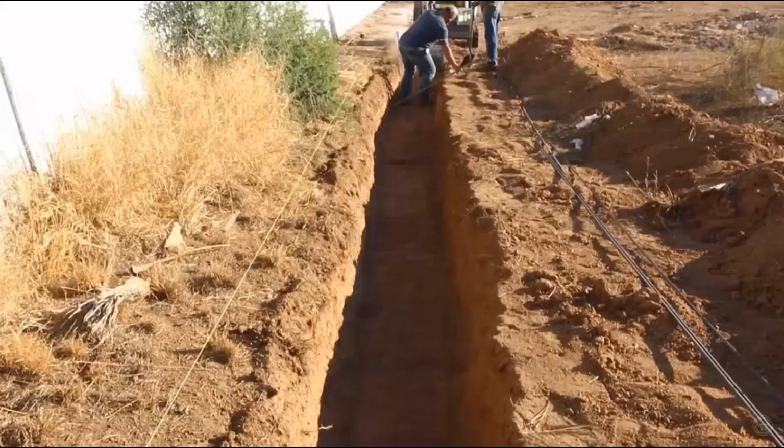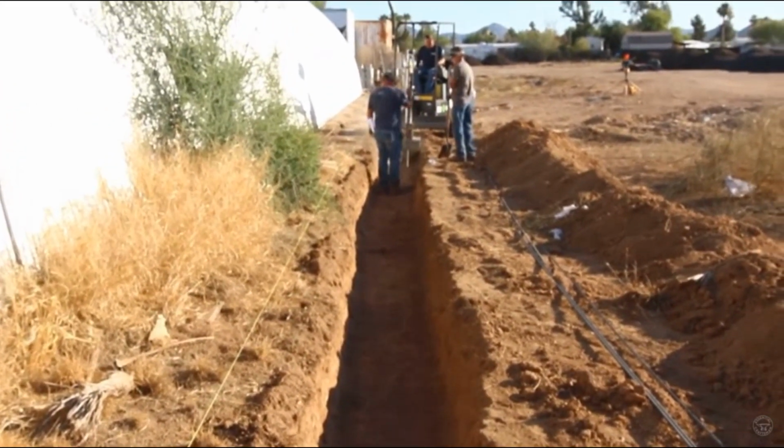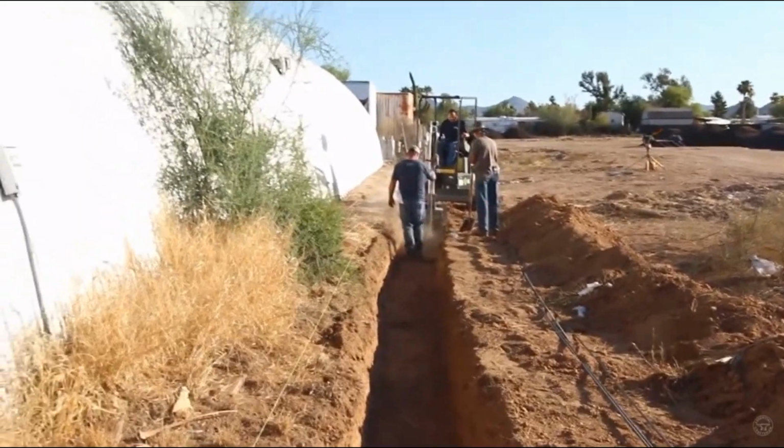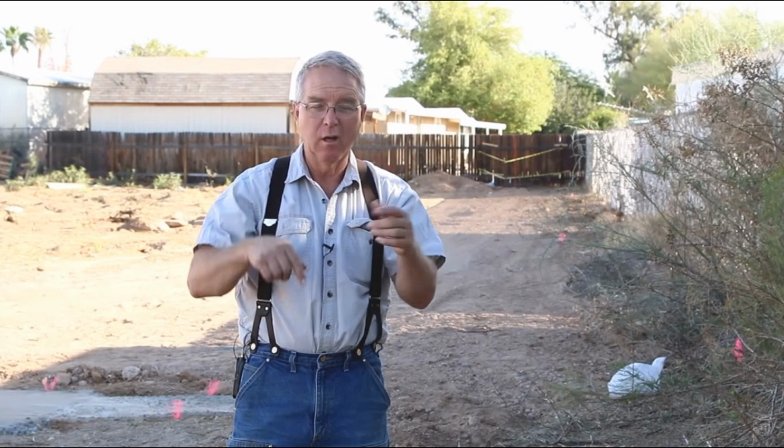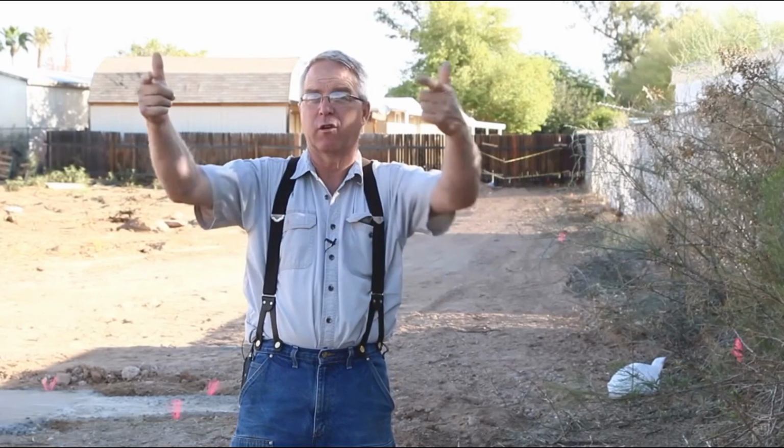The first engineer to weigh in was the geotechnical engineer. He had to establish soil bearing capacities. The soil bearing capacity is information the structural engineer has to have to determine how wide the footing needs to be to hold the load, not just of the wall, but of the wind loads and overturning moments, because this wall is only braced at the corners.